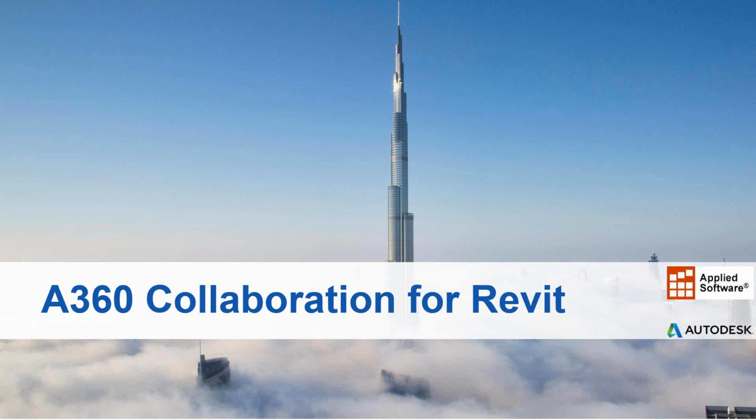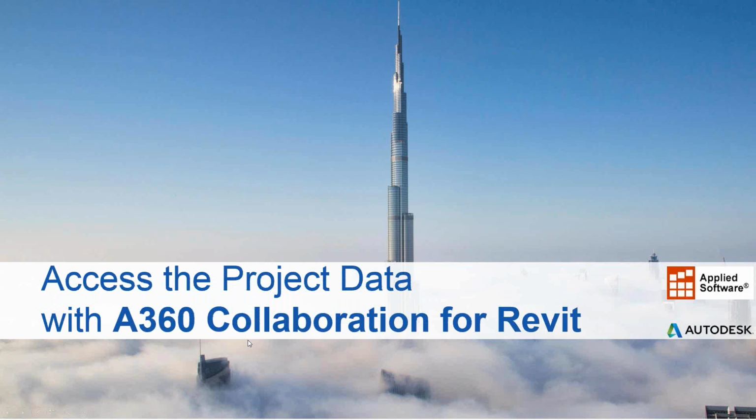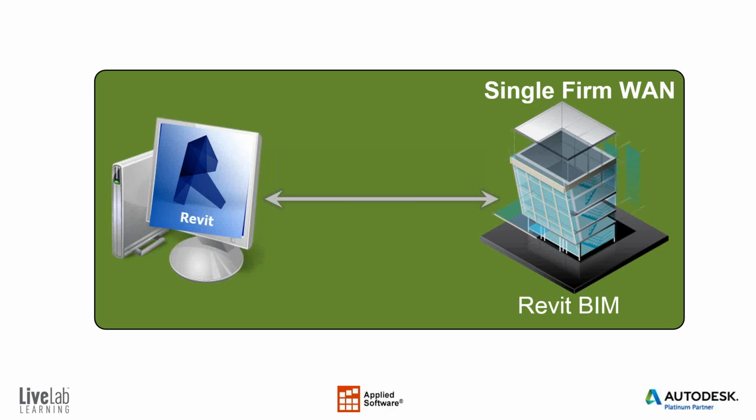Let me just kind of talk about this in general first, and just talk about how we access the project data and kind of what it does. If you're familiar with how Revit works with work sharing, if you're working on a Revit project and you need to have more than one person working on that project, you will enable work sharing, and typically that will create a central file, and that central file will reside on your network, and then each user will come along and create a copy of that and work on their local copies.